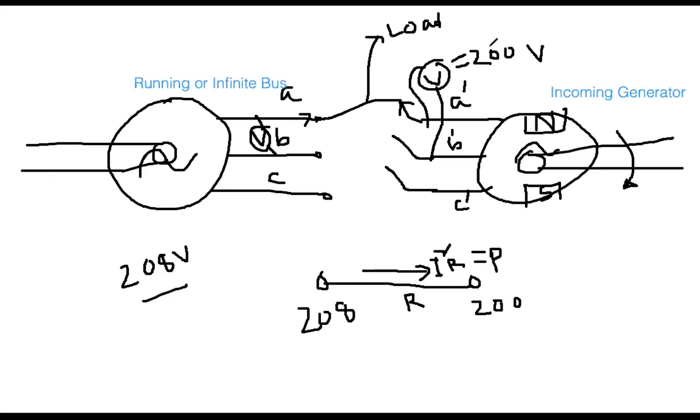For example, you made this one 220 volt, just an example. So if it is 220 volt and this side is 208 volt, then current will start flowing from this side to this side. Then again the same problem. There will be I squared R, heat generated and undesired losses. So parallel connecting means you want to support the customers. You want to contribute to the loads only. It is not your goal that this generator and this generator will exchange power.